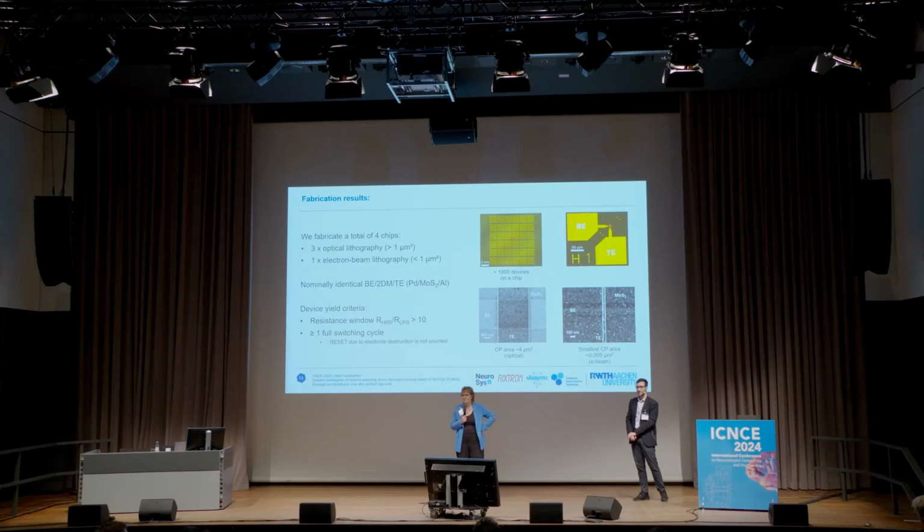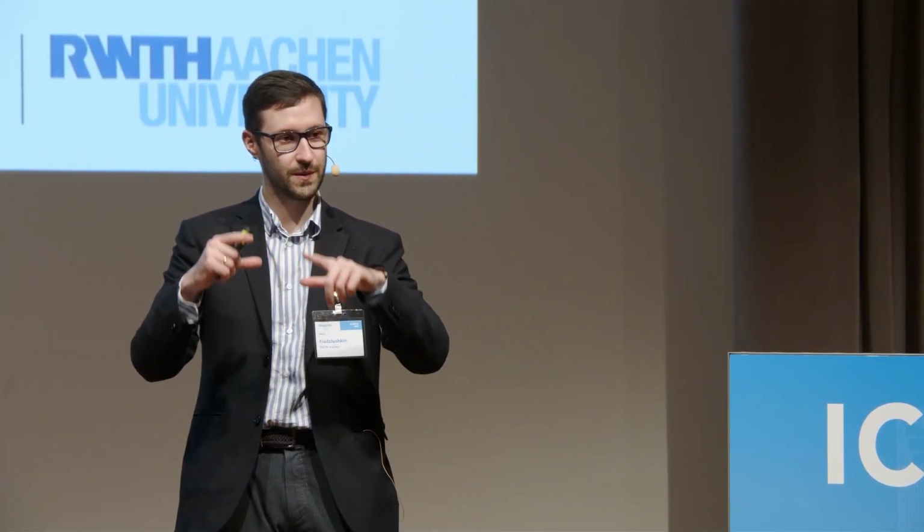With regards to crystallinity, this is something that we are still working on. These samples are typically polycrystalline. They grow as individual domains that during the coalescence form a lot of grain boundaries, for example. So we're not talking about single crystals here, definitely not on the wafer scale, since domains are usually of the size of several hundred nanometers in the best case.